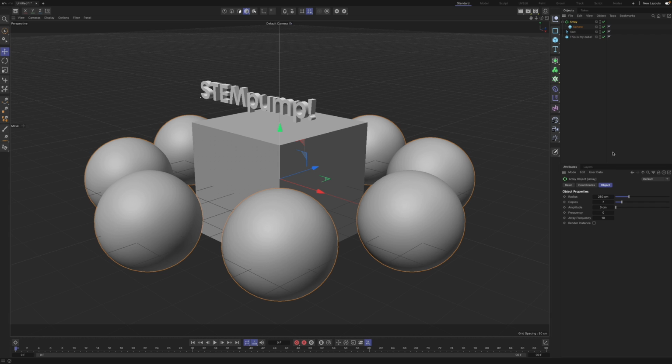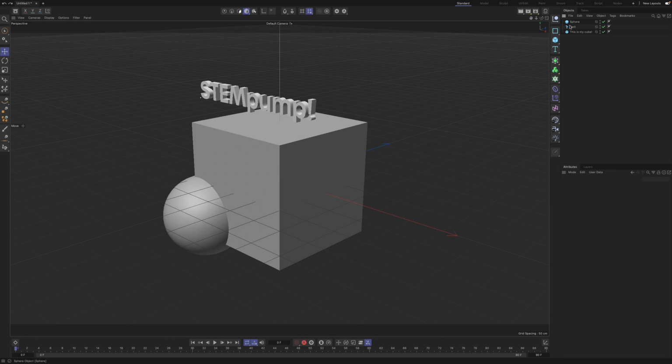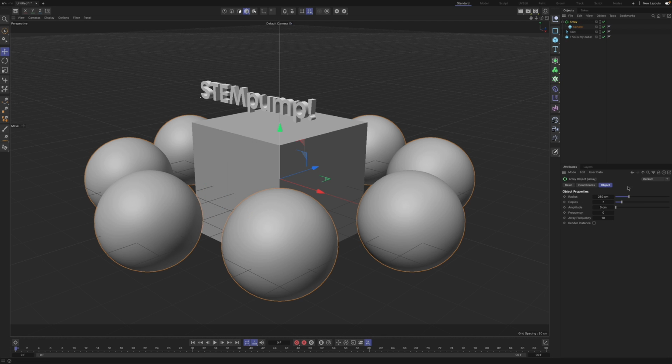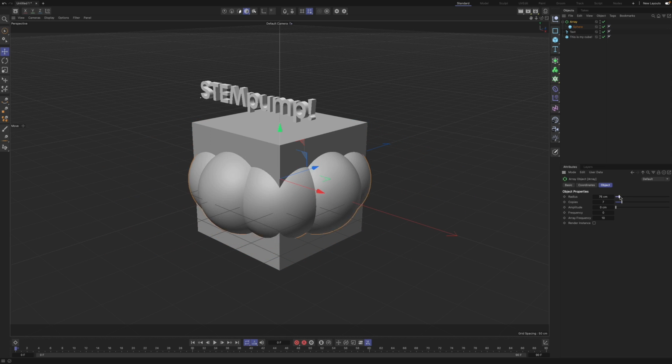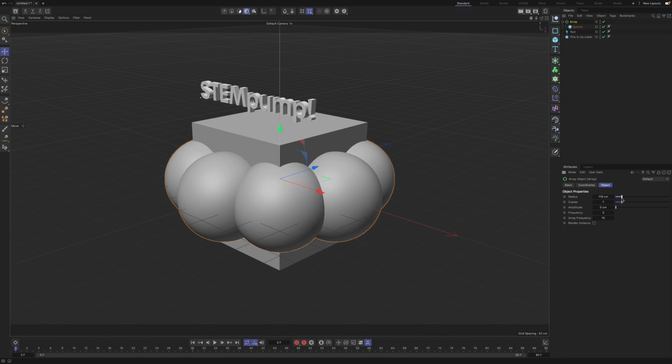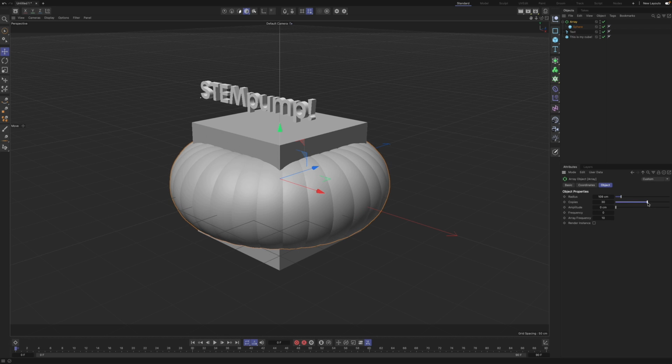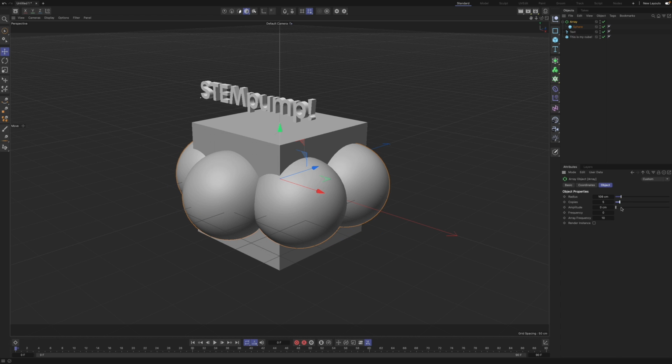You can click on the array. And the way I did that was just literally create the array, just drag it on it so you can see this little down arrow, and then it just creates it. Then we can click on the array, and you can see the radius when we increase it. So maybe we'll do like that. We can do copies, so how many of them we want. So we can go a lot. I'll just stick to 5.